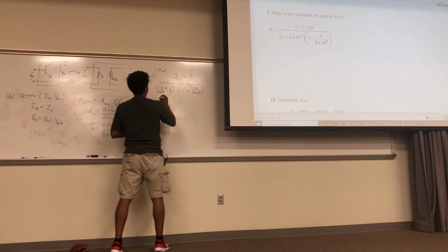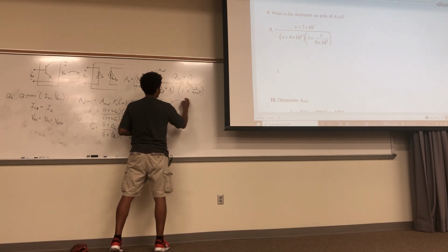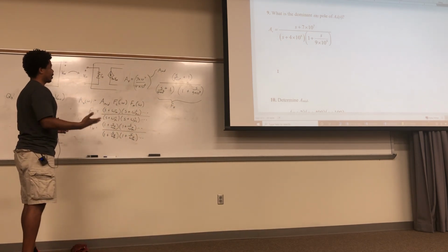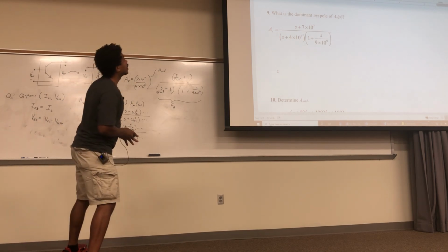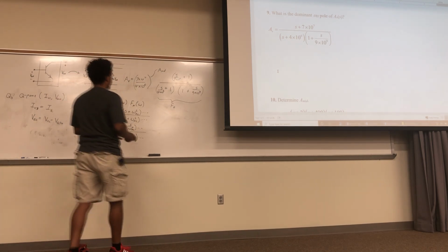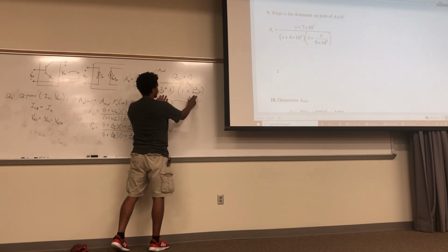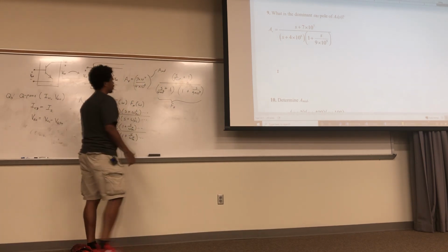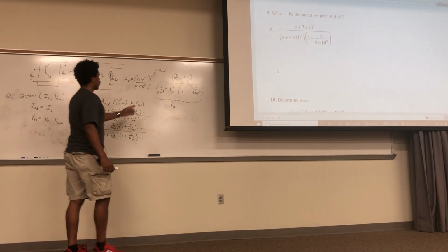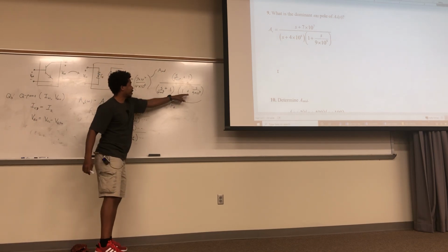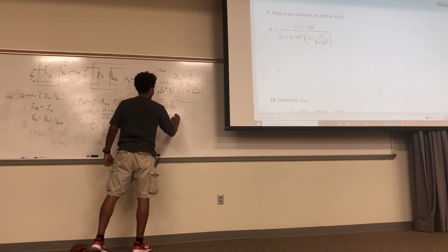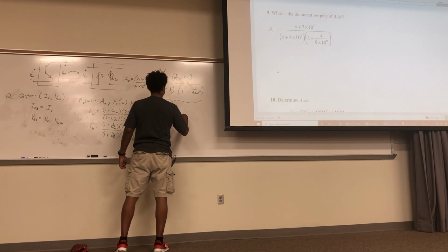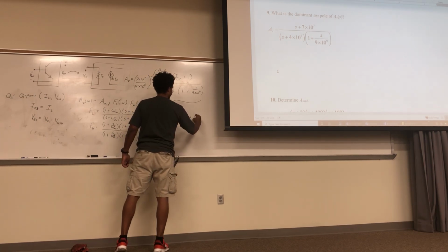So this is A mid. All this right here corresponds to our FH. And we don't have anything that's like really low frequency stuff. Okay, so now the question is the dominant pole. Okay, so we have 2 poles here, right? The dominant pole in this particular case is going to be this one, because this occurs first before that one. Okay, so here's our dominant pole. So in this case, you would say omega h is like 4 times 10 to the 6 radians per second.